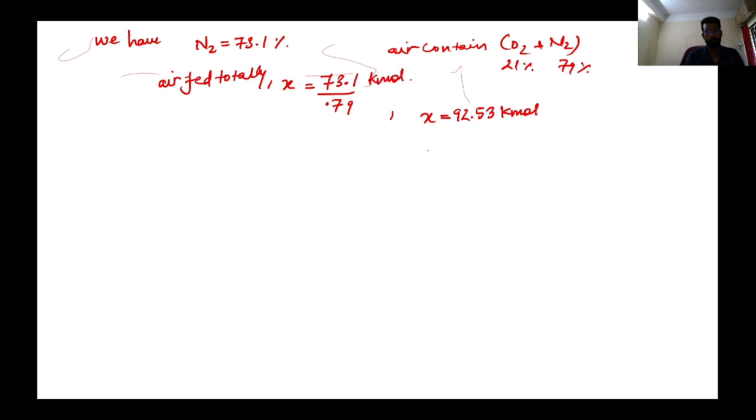Okay, now this is air fed. One thing we have calculated, air fed totally. Now theoretical air required. So for theoretical air required, first we have to calculate how much C3H8 has been reacted.